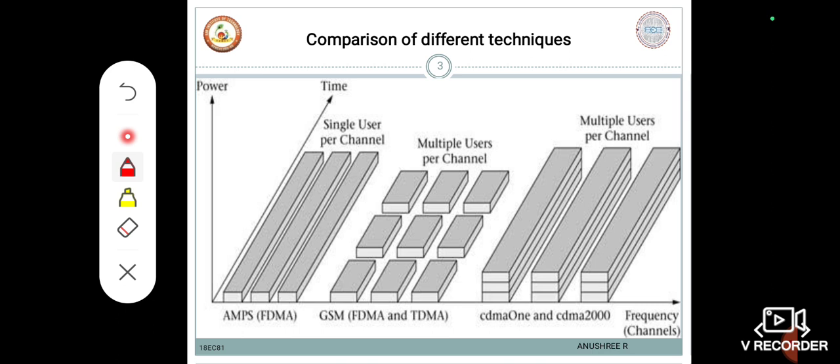Now, how are the frequency planning issues handled? Because of a frequency reuse factor of n equal to 1, CDMA frequency planning is relatively simple compared to the analog cellular system. For a system that only requires one carrier per base station, that carrier must be chosen properly from the list. The same channel should be used by all the base stations throughout the system to take advantage of soft and softer handoff capabilities that are possible with CDMA technology.